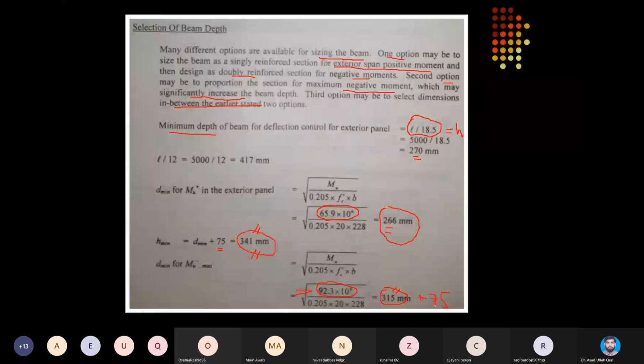So it has half of 3.5 on this side, it has half of 3.5 on this side. So you mean that all the slabs center to center will become integral part of this beam which is running over the column.